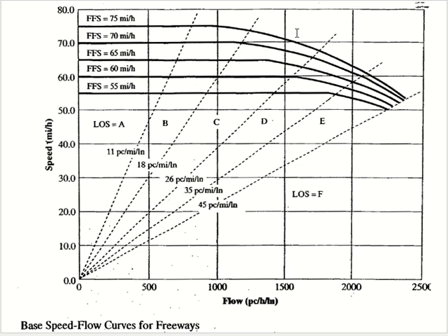We have flow rate, right? Do I have speed here? We have. Okay, so if you do flow rate upon speed, it will become what? Density, right? And density can give me level of service. Okay, but if I do flow rate upon speed, what will I get? Flow rate is on the x-axis and speed is on the y-axis. If you do flow rate upon speed, which is density, so density is the inverse of the slope, right?